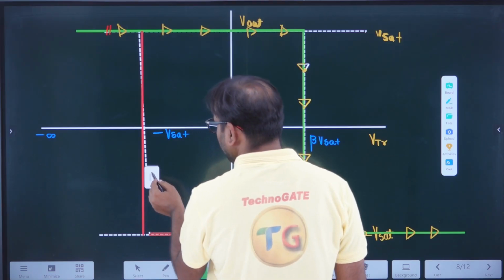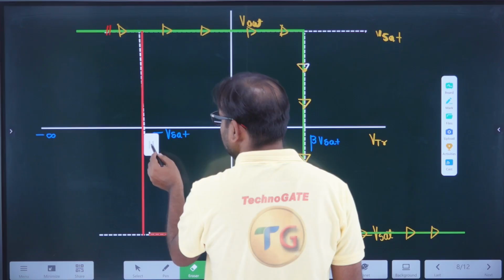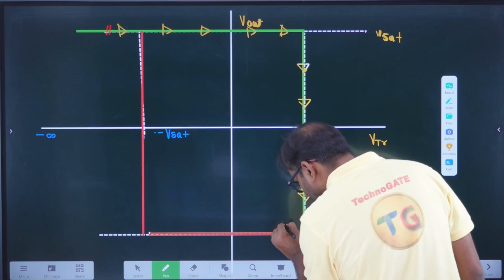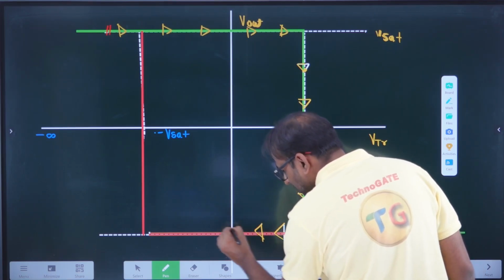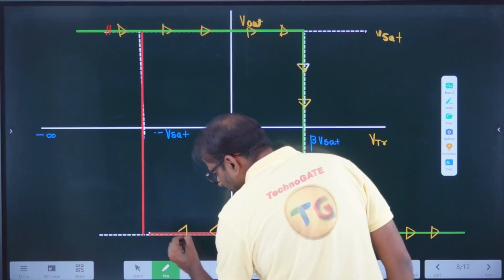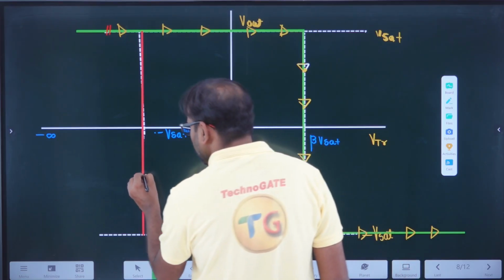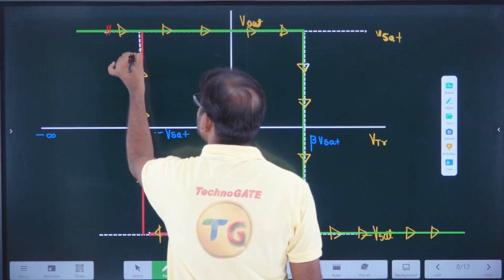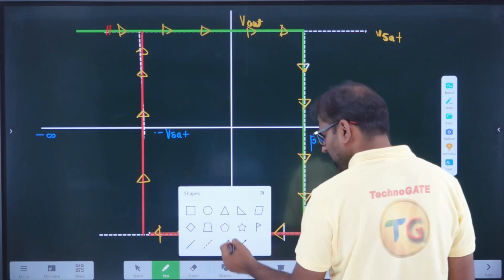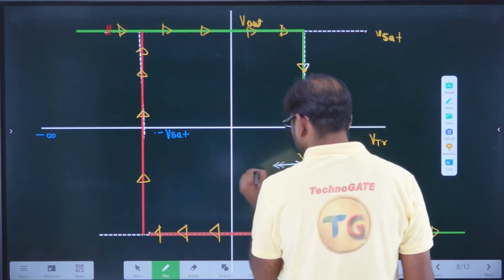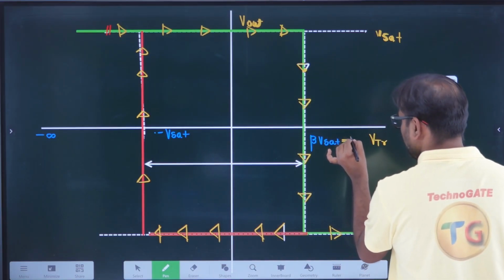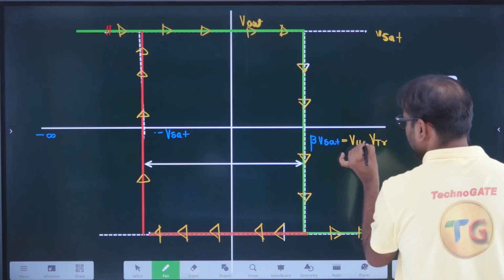This is the curve for which your system lies in which range? And what is the direction of the arrow? The direction of the arrow is always the direction of change. So this is one hysteresis curve you can have. And what is the value of the hysteresis? What is the thickness of this curve? They call it the upper threshold.